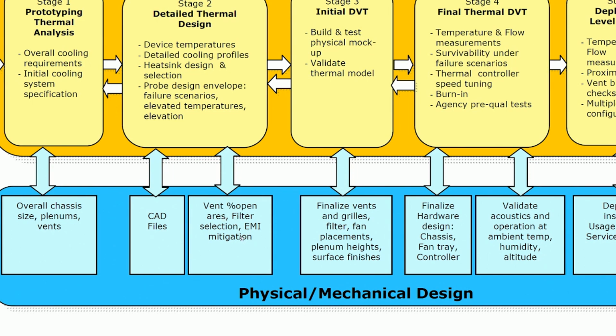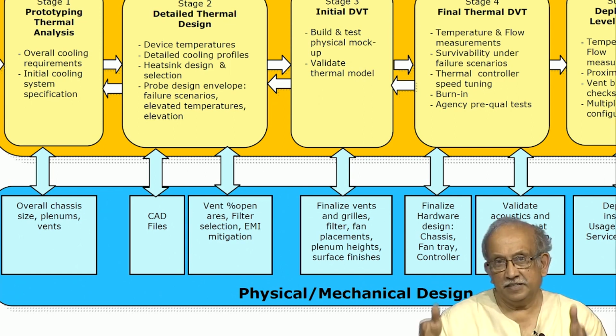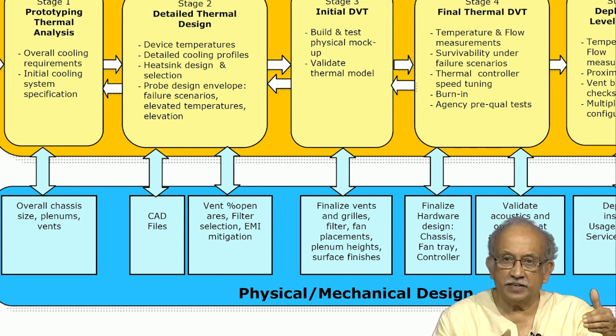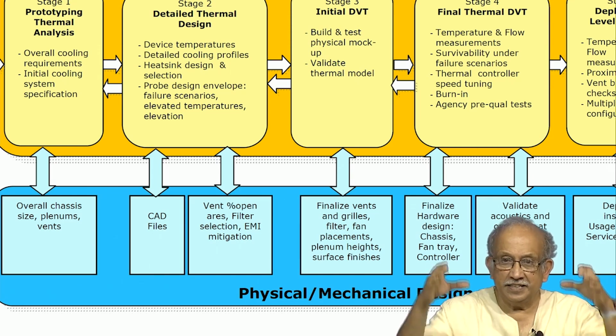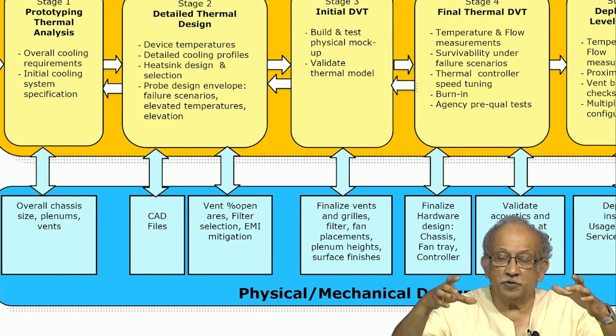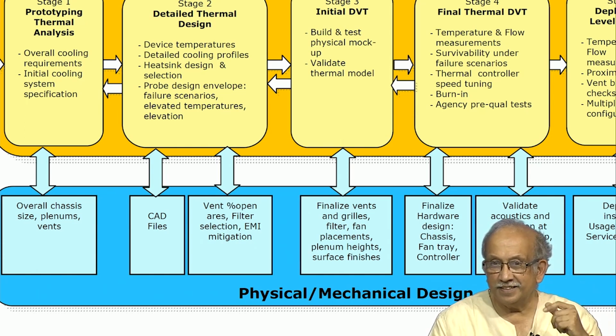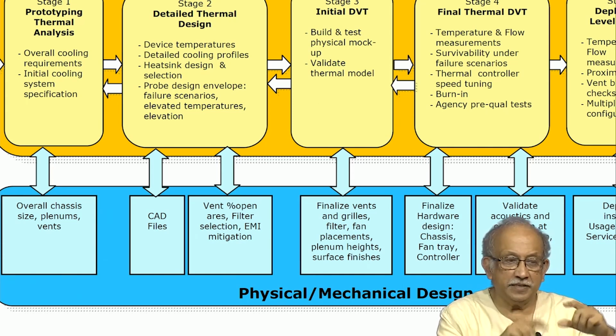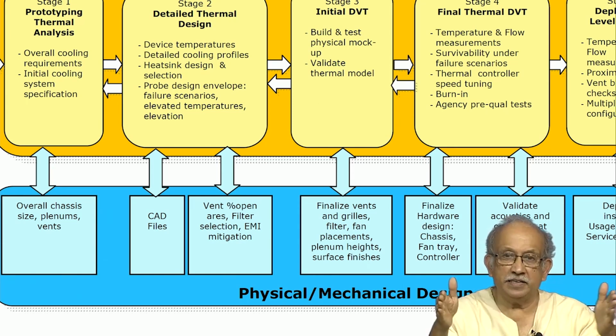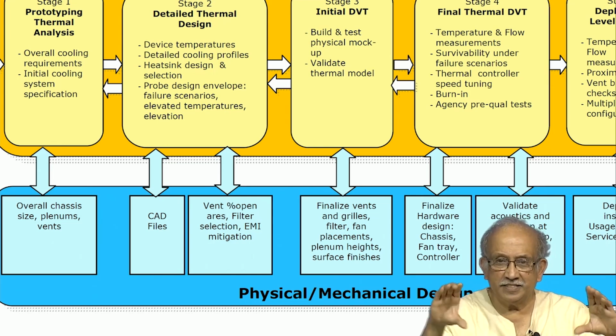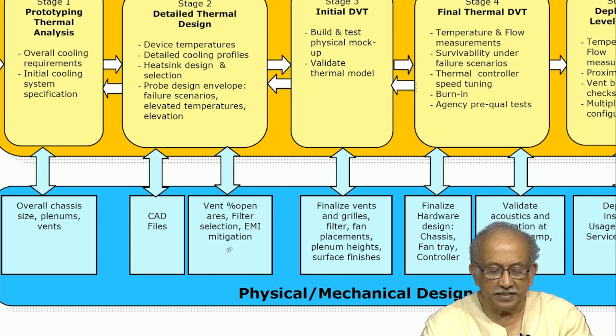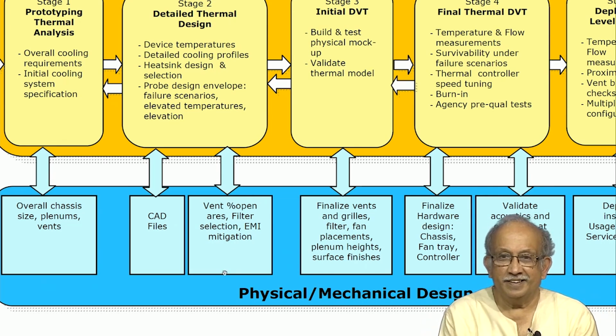percentage of open areas. While the cabinet itself may be big, meaning you have say some 450 mm by 450 mm cross section, the actual spacing for the air to move will barely be about 20%. Again, a vent itself may be about 100 mm high and 400 mm wide, and you usually have some grill on it. So, that is where the filter comes. You cannot ignore a filter even on the outlet side.